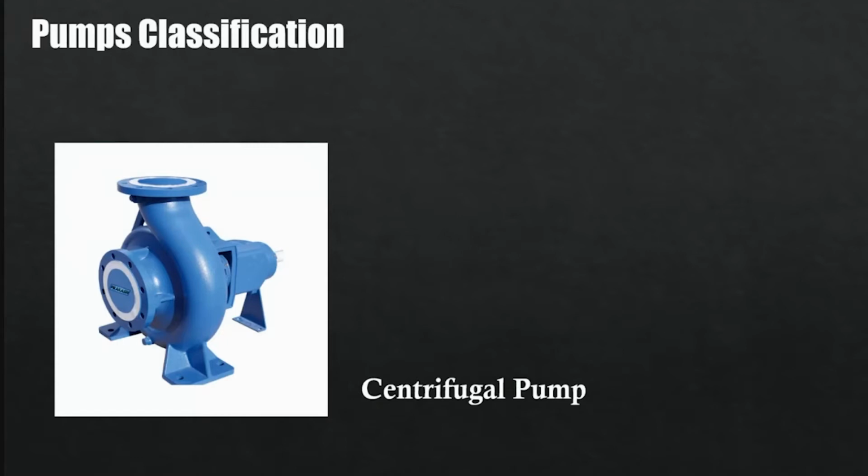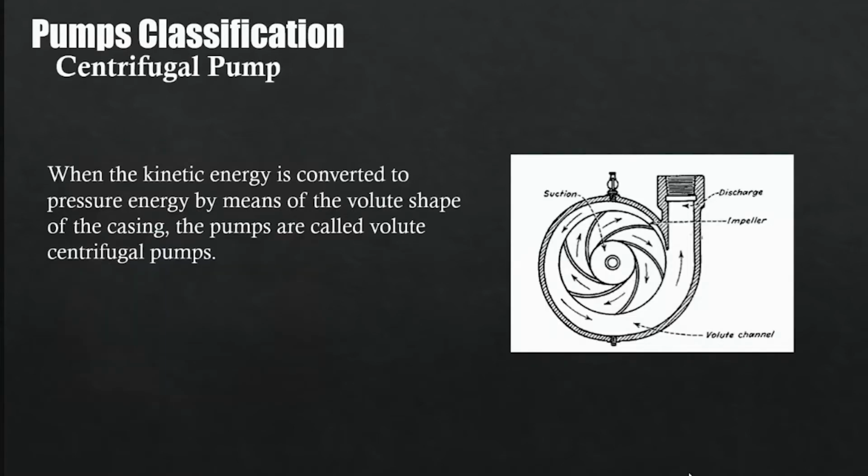The first classification of pump is the centrifugal pump. It is used to transport fluids by a conversion of rotational kinetic energy to the hydrodynamic energy of the fluid. The rotational energy typically comes from an engine or electric motor. They are a subclass of dynamic axisymmetric work-absorbing turbomachinery. These are the classifications under the centrifugal pump.